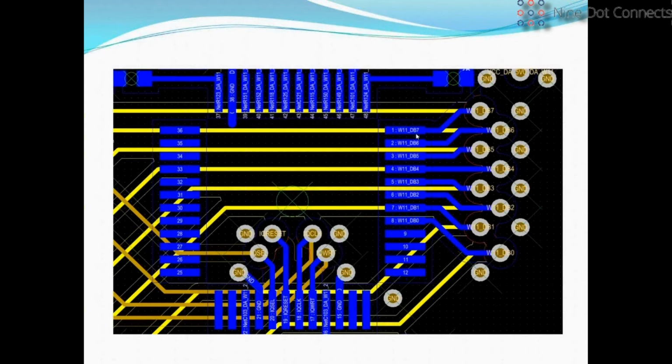So it's very common that you're going to have not only digital, but power supplies and RF circuits all on the same board. They do compete with one another, and as Paul mentioned, you may have a 3-mil line in one fine line BGA area where you've got big giant traces in another part of your board. So we'll get into copper thickness a little later in the talk.